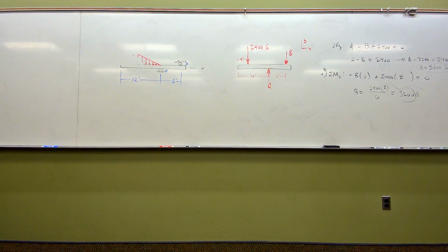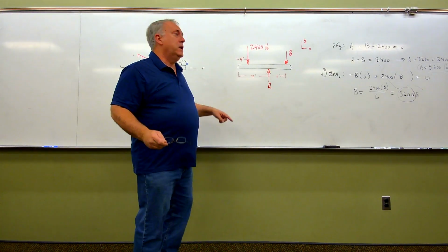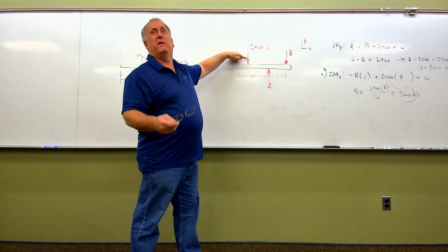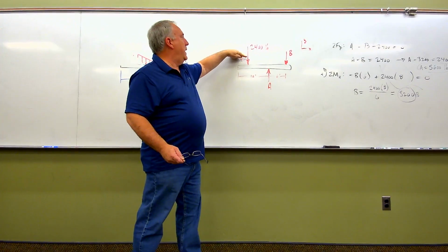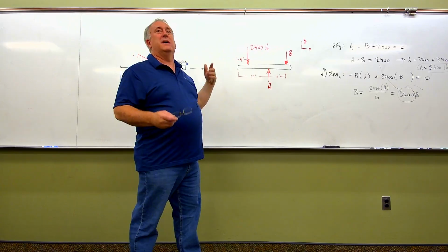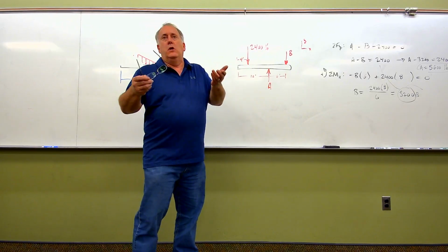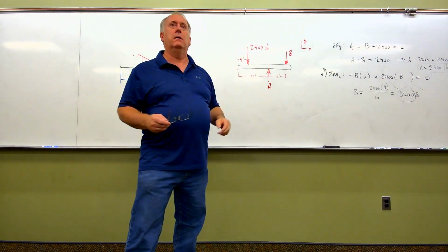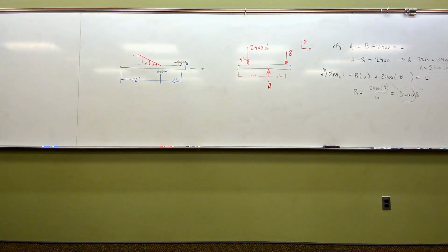Great question. So Nate's question is, so make sure everybody hears it, does the Y direction matter? So Nate, to your question, we know that the Y location of the centroid is somewhere up like where my finger is, right? But the reality is the force passes through that centroid wherever it is. So it doesn't matter where the height is, because what does matter is this location right here. It's a great question. What other questions might you guys have? Good stuff. These are the kinds of questions that are really helpful.